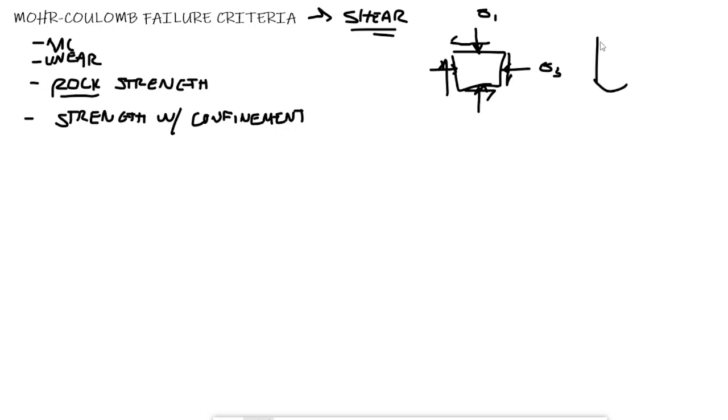To draw this picture in a more practical sense, this is what you'd see in a laboratory. What you'd see in the field in situ is going to be different again, but for laboratory testing, this illustration works quite nicely. You'll have a core, a cylinder of rock that's been cut, ground, dried, all of this to specific specifications that are going to allow us to keep the results uniform, predictable, limit the amount of variability. You'll have sigma 1, that's for a uniaxial compressive strength test, and then when you go into a TCS, triaxial, you'll have some sigma 3.